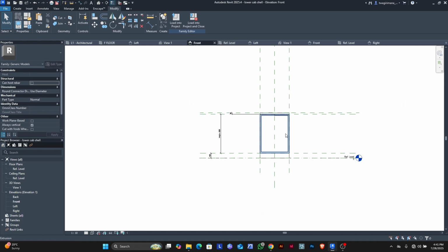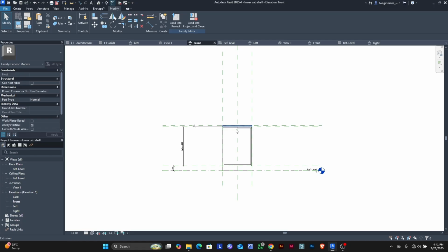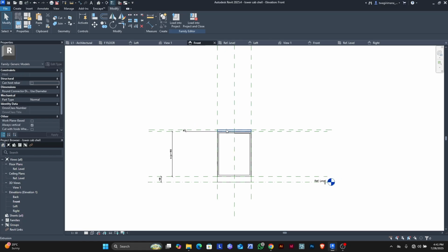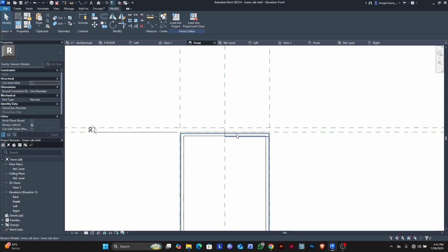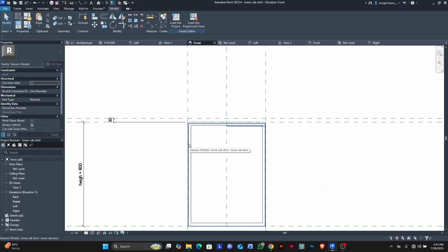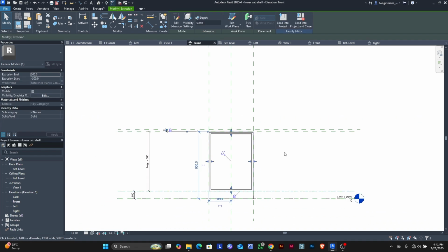So the long cabinets will be, let's go to the front view. So our long cabinets will be, we have to add the partitioning or the shelving. So we have to first remove what we don't need in this family. So we don't need the countertop for long cabinet, so let's delete it. We don't need the handle to this door, so we need to edit this door later. So what we need mostly is the partitioning